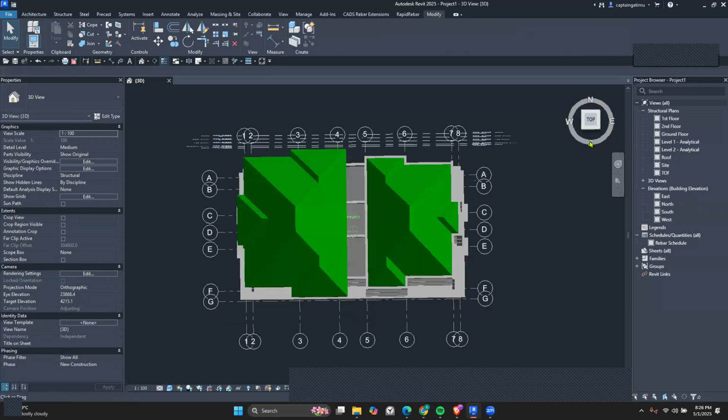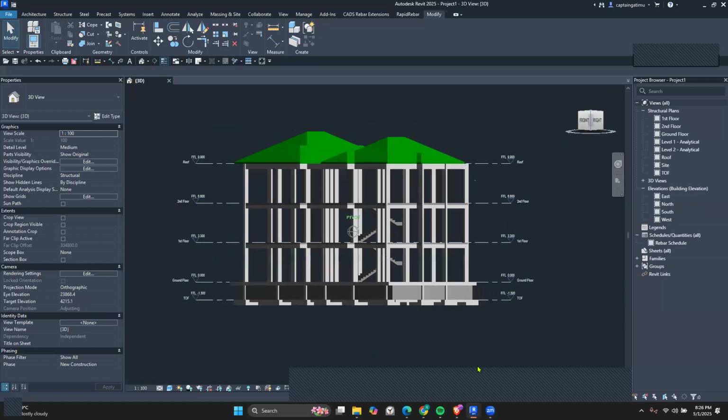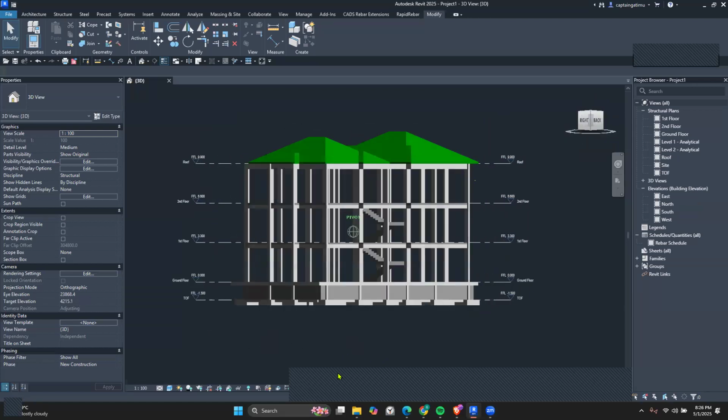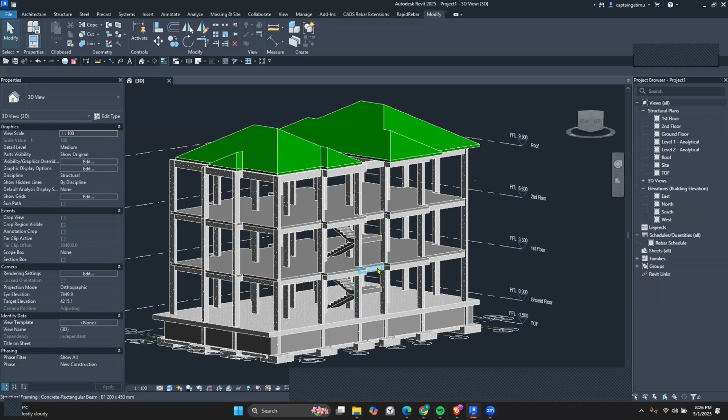From the top of our structure, you cannot see a staircase. Where we have our staircase, we also have a slab. Someone cannot walk through this staircase and go into the upper floor because there's a slab modeled or cast there. This is not what you're going to have on site, and it's also not ideal to have it in your details.